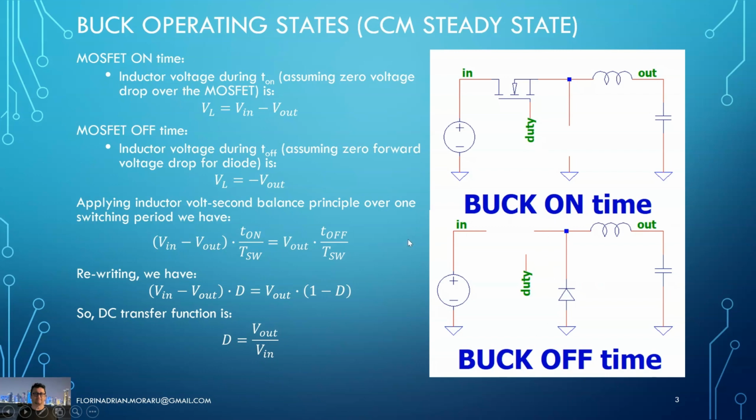In order to get the ratio of the duty cycle, or the DC transfer function as it is often called, we need to apply the inductor volt-second balance principle over one switching period. So actually, this is what I put here.